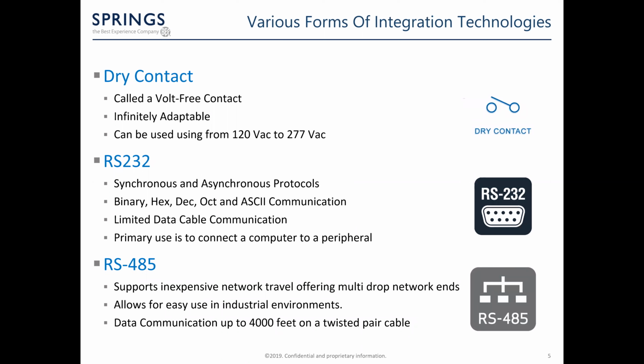Now we'll discuss the key points I'd like for the dry contact technology. First, it's called a volt-free contact, which is a relay contact that does not supply voltage. The relay is not wetted by a voltage source, giving it the name dry contact. The relay energizes or de-energizes when a charge comes to it. In other words, a dry contact simply detects whether an input switch is open or closed.